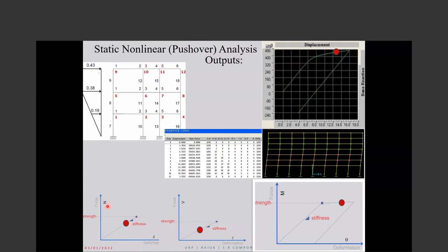And for the element, the section area is given, the stiffness and the material properties, the E. Even you have the stiffness. Software has the stiffness. So there is no new thing for the force control action, except that when we calculate the strength, in the formula we put the lower bound value for the material properties. Other than that, there is no problem.